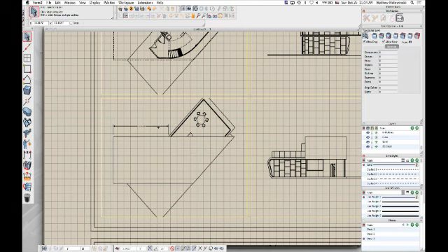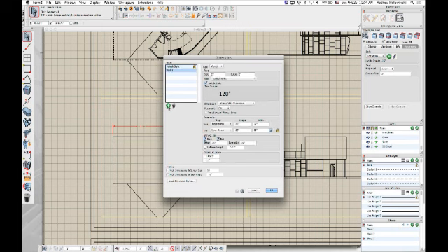If you need to control that with a parameter, when you set up your dimension styles, you can see that in that style, not to create a new one here, there is an option down here to hide those if they get within a certain tolerance range. So make sure you don't have that on, because that helps so that if you're zooming way out, you don't want to see the text there. You only see it if you're close enough to see the actual text. So make sure that option is not on for that.